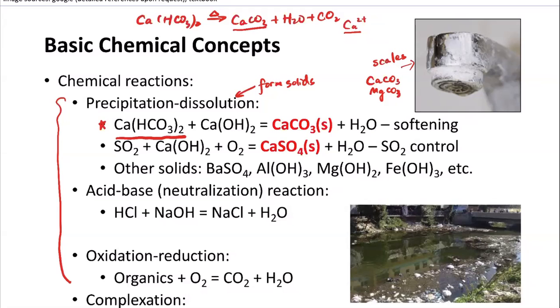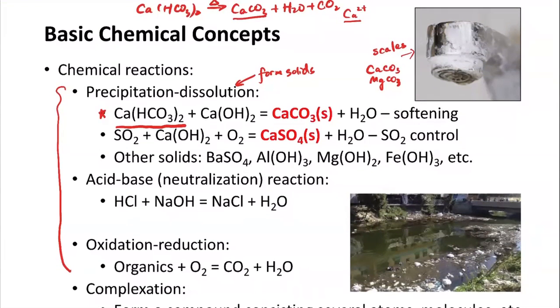Okay, so actually, the way they did it is by using this reaction. What happens is they introduce calcium hydroxide into the water. They obtain calcium hydroxide, again, from rocks, okay? The rocks are mainly composed of calcium carbonate. They can bake it, generally at thousands of degrees Celsius, to form calcium oxide and carbon dioxide, right? And then this calcium oxide, you can just submerge into water.